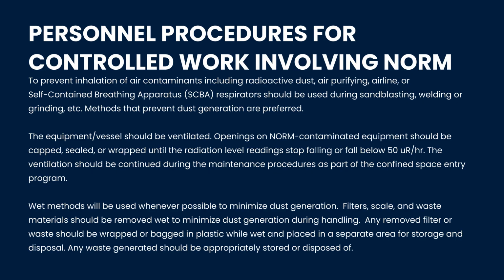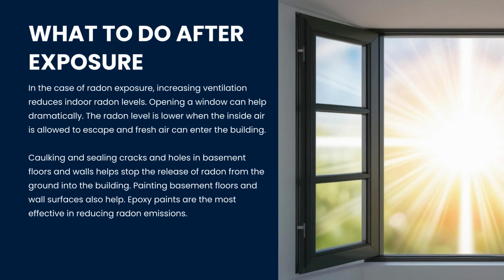Activities that generate dust, such as grinding or welding, can increase exposure risk. Using ventilation, wet methods, and proper containment helps prevent airborne contamination and protects workers. If radon exposure is a concern, improving ventilation is one of the most effective controls. Opening windows, sealing cracks, and using protective coatings can help reduce radon levels indoors.